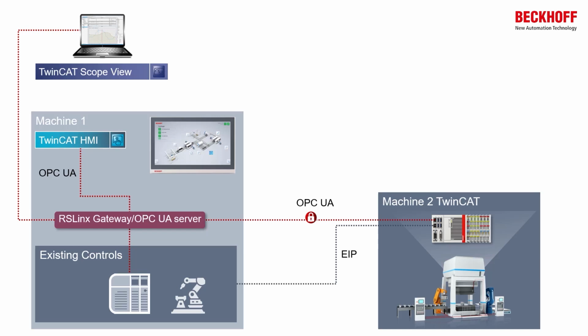And in this example, we're going to use the server client architecture from OPC UA. But in the very near future, TwinCAT's also going to support the OPC UA pub/sub specification for controller-to-controller communications. So stay tuned for more product announcements and future webinars specifically on that functionality. So in this case, we're going to set up this controller-to-controller using OPC UA client server, and the TwinCAT side, machine number 2 in our little example here, is going to be the OPC UA client.